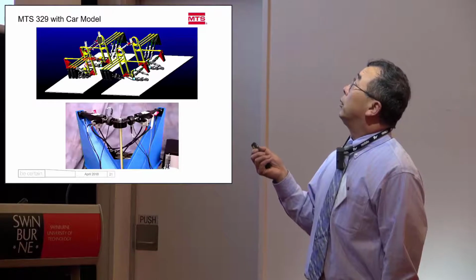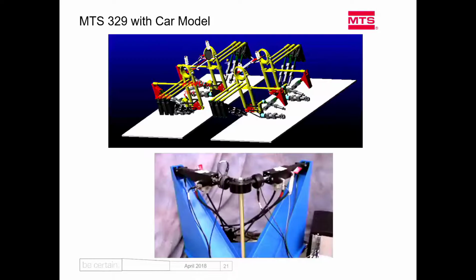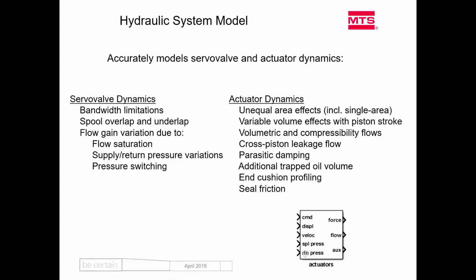Same thing, so we did another example. There's a car model, not shown here, to show you the test rig, and the test rig has 24 actuators and 24 control channels. Inside this car there's a spring, represented by this column, and we use Adams coupled with OpenFresco, coupled with this test rig, to do real-time hybrid simulation. That worked well. Yeah. So that's hybrid simulation.